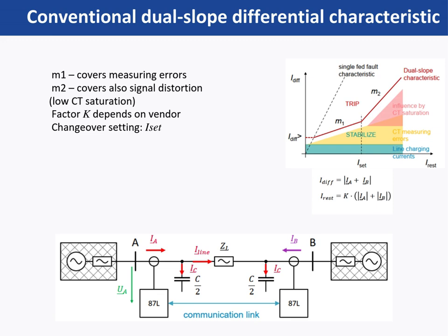To summarize, line differential protection is a fast, selective, and highly reliable protection method. By directly comparing currents at the boundaries of the protected zone, it provides instantaneous fault clearance.